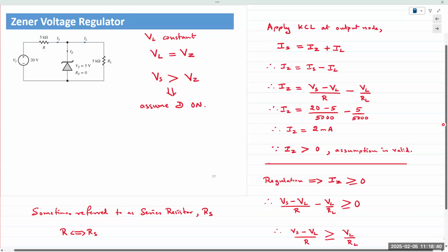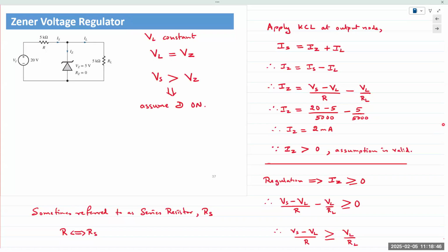As an example, we plug our electronic devices into the wall outlets, and we expect it to be 110 to 120 volts. We expect that to be constant, but there are always fluctuations in the voltage. During times of high demand, the voltage would drop a little bit. During thunderstorms, lightning, you might have a spike in the input voltage, which could damage our devices plugged into the wall. So we would want to isolate our devices, meaning our load, from any change in the input voltage, right? And that's where the Zener diode comes into the picture.